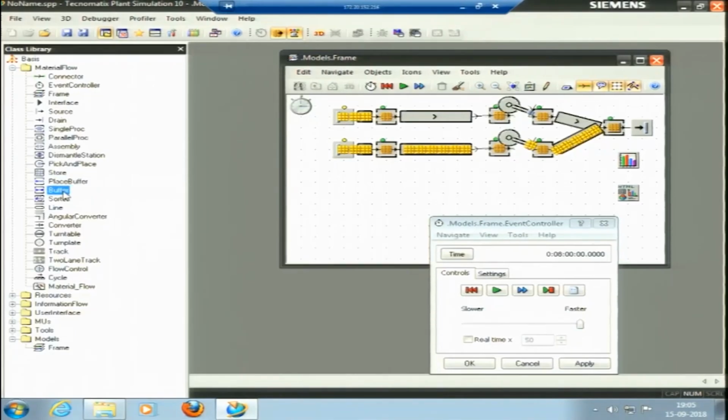For a buffer with a great capacity that requires high performance, we can use the buffer, like I said. So place buffer is a small thing. The big buffer is placed between two plant components for certain purposes. It temporarily holds parts when the following components fail, when the successor is not able to receive the component. The second important function is that it passes the part on when the preceding components stop working. A buffer with large enough capacity for covering all failures leads to complete decoupling of the plant and the other attributes as well.